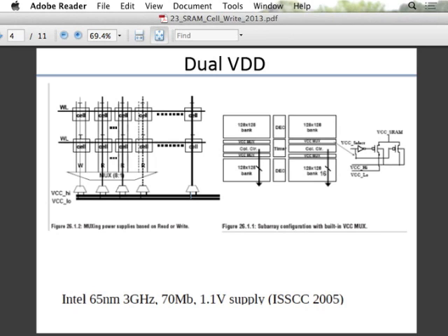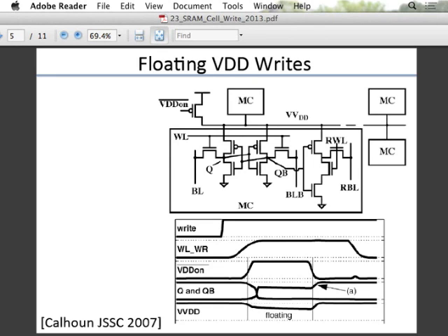So hopefully during that duration, the cells which you are not writing, their noise margin has come down because you have reduced the voltage. So they can become potentially more vulnerable during that time. Like here, only one additional row is made vulnerable. Now you can say I will have separate VDD for each row. So then you make that even more robust. So only the row you are writing, the VDD reduces, the other rows remain where they are. But that means extra area. The reason they have done it this way is they are sharing this.